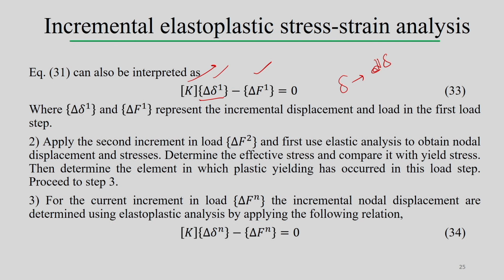Once you solve this equation, we reach the incremental displacement field, then we convert to the strain, and then to the stress in the incremental way. We can add all these to what we got in the previous iteration. Therefore, delta 1 and delta F1 represent the incremental displacement and load in the first load step.